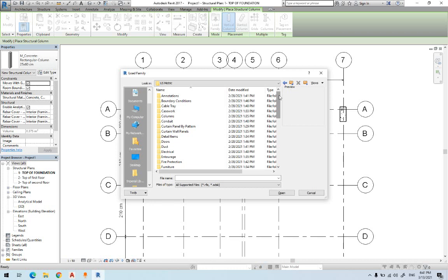You can download a lot of families. So what is a family? Prepared shapes that you can use for your project. You don't need to create them from the beginning. It is divided into different categories. There are columns here, but those are architectural. At the bottom you'll see Structural, for example structural column, structural connection, foundation, framing, rebars, trusses. Anything that we want, we can bring it.